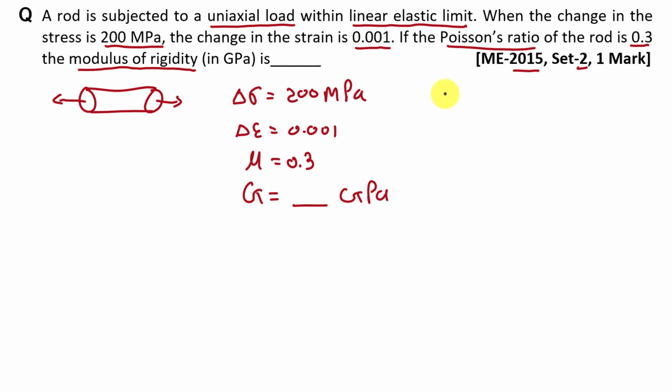Now see, we know the equation that sigma is equal to Young modulus into epsilon. And we know that in the stress-strain diagram, up to proportional limit it is a linear line like this. Here there is engineering stress and here there is engineering strain, and the slope of this line is Young modulus. Now this is the equation from zero loading condition, means if we apply this stress value from zero loading condition, then this equation is satisfied.